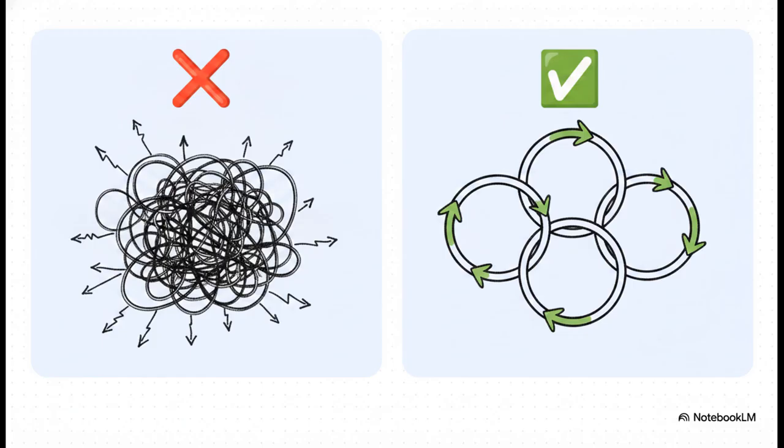Well, the culprit for all that hair pulling is almost always the old branch method. It creates this chaotic web because you're literally tracking every single wire and every junction split. You end up needing a massive system of equations, one for every single branch, which is practically begging for human error. But the mesh method, it is a total game changer. By zooming out to track continuous closed circular paths, we get to completely ignore those junction splits. This drastically cuts down your independent equations and is perfectly optimized for complex, multi-source systems.